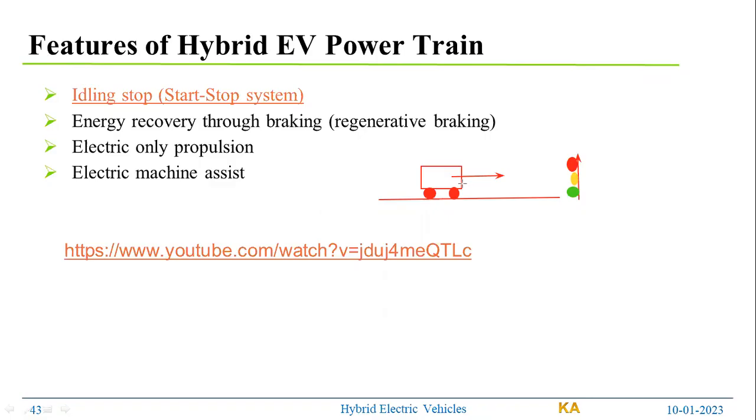So during these traffic and go situations, or in an urban condition like buses, where there is very frequent stop and start, during this time as well you require a mechanism where the energy should not be consumed during the steady state, or the consumption of energy during this state should be reduced. So how do you reduce? That will be possible when you have a mechanism of a basic hybrid philosophy.